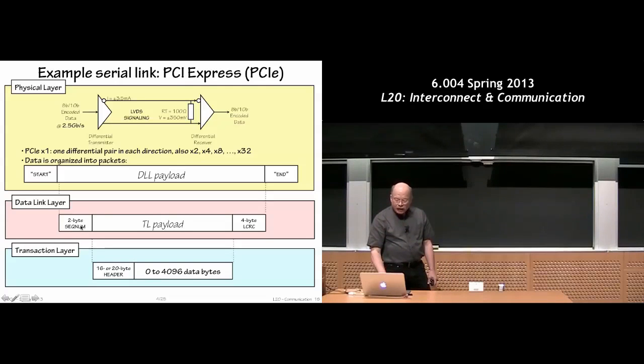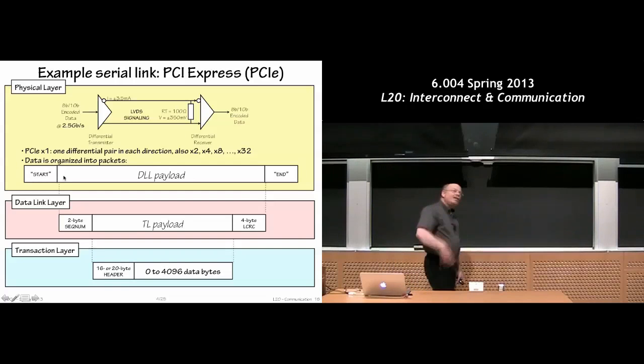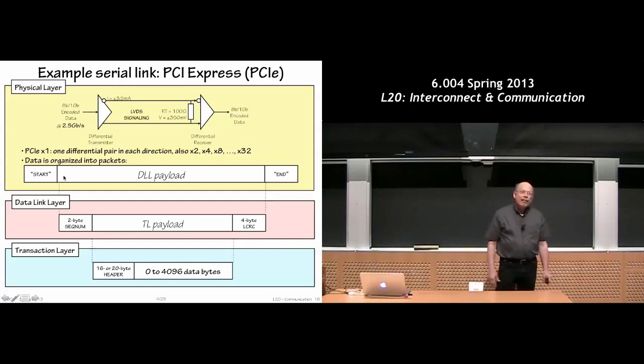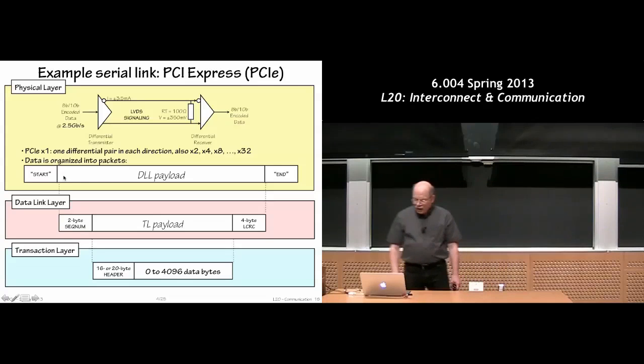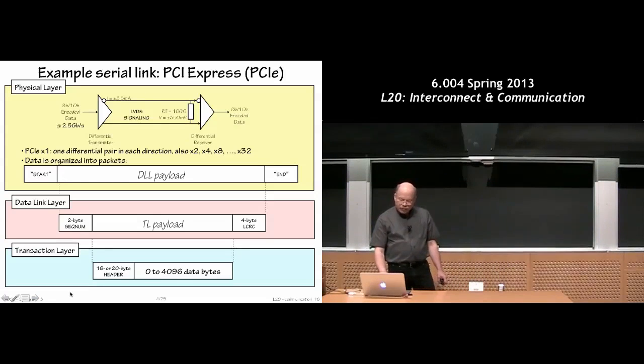That's packetized and broken up into a whole sequence of packets, and so we have a sequence number for the packet. This whole thing is protected by a CRC, so we can tell if the payload has been corrupted. We then stick basically a synchronizing sequence at the start and the end, so the low-level electronics can synchronize the clock recovery and figure out when a packet starts. This is all covered in 6.02, probably more than you wanted to know.